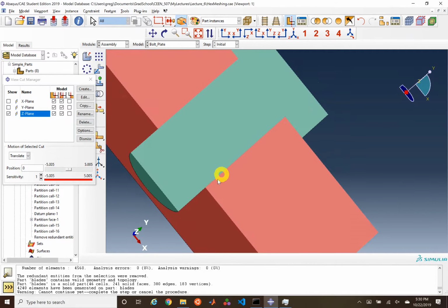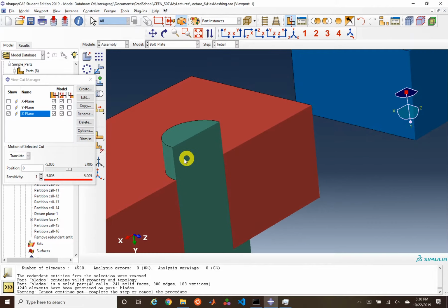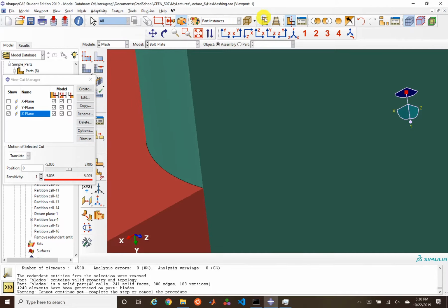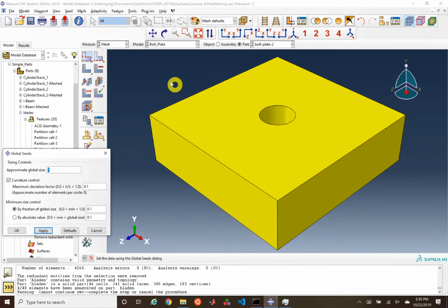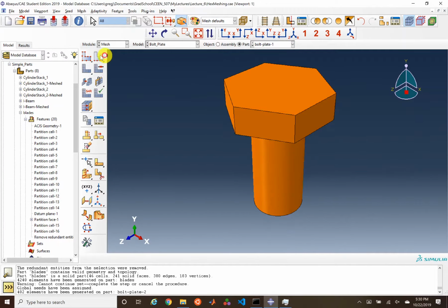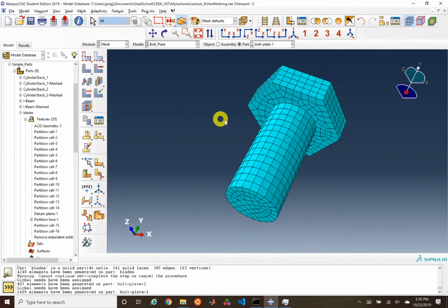All right, so this bolt is a perfect fit into this plate. The geometry is exact, two exact circles that exactly match. But what we'll see is if we switch over to meshing, if we take this geometry and do a mesh on it, and we take the bolt, we can get ourselves a simple mesh by partitioning with this face here and throwing a mesh onto this guy.